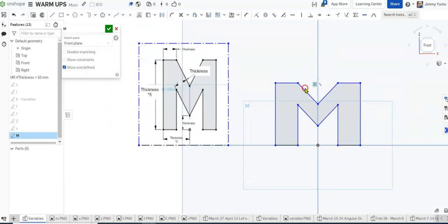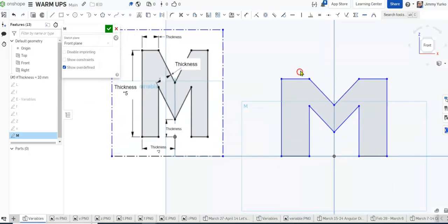All right, now let's go ahead and apply our dimensions. The dimension is thickness. It's our variable, which we established earlier by clicking the shift to number 3. We already created a variable called thickness. We can reuse that. If I want to create a new variable, just click the new variable button and then follow the instructions.